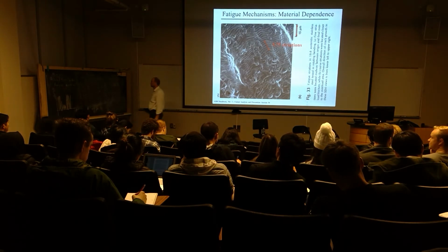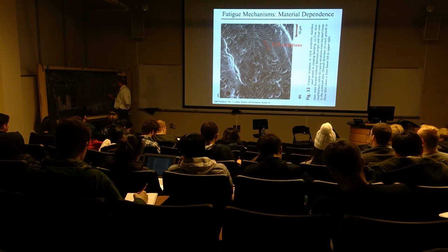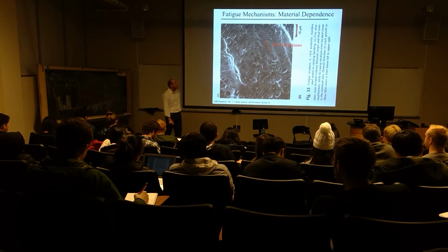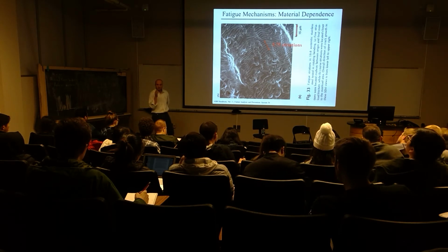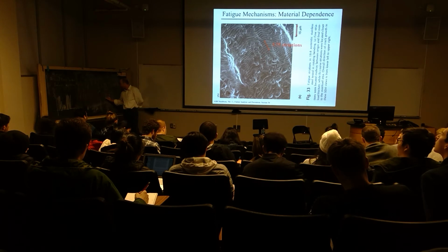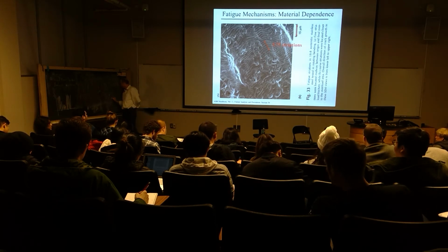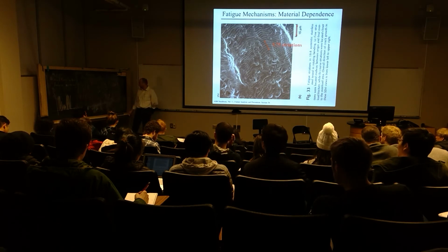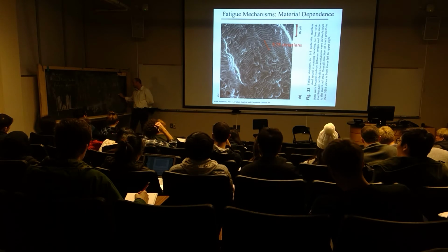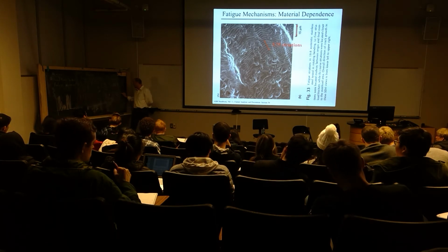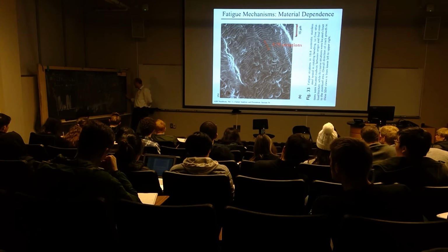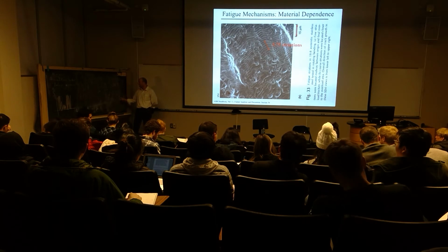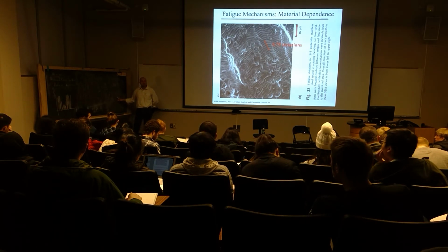So it looks like that crack went 15 micrometers divided by my 5.75 striations. A striation in this material is a result of a cycle. So that's actually 5.75 cycles, right? And I forgot my notes. If I remember correctly, that's about 2.6 something times 10 to the minus 9 meters per cycle. You might want to check that, because I'm trying to remember what that number was. So that gives me the dA/dN, right?